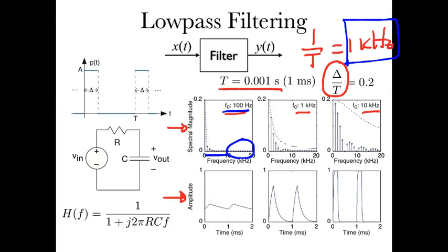When the cutoff frequency is now 1 kilohertz, which is right at the first harmonic, it won't be suppressed very much, just by 1 over the square root of 2. You can sort of see the pulses coming out, kind of. It's not clear the original were pulses. You tend to get what I call the shark fins. So it goes up and it comes down. It goes up and comes down because it's periodic. The output is periodic, of course.